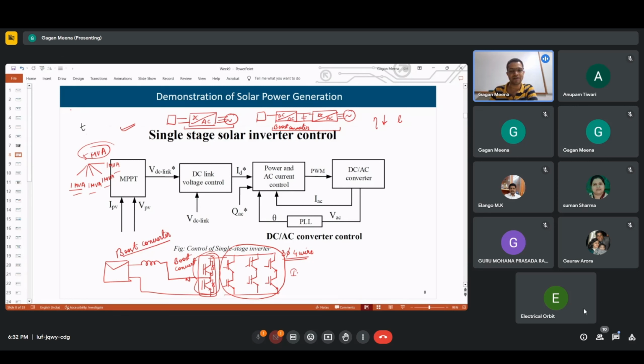One of the drawbacks of fast charging is that SOC cannot go beyond a particular value, like maybe around 70 to 80%. Beyond that, it will not increase. So fast charging is done up to that in current control mode, and after that the power is reduced and it works in the constant voltage region, because initially we don't want to increase the current, never.